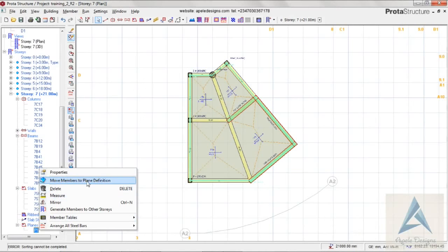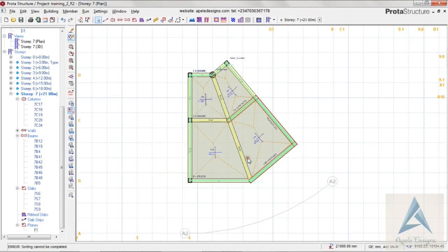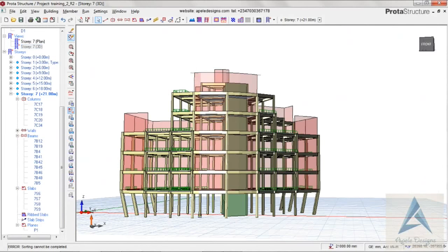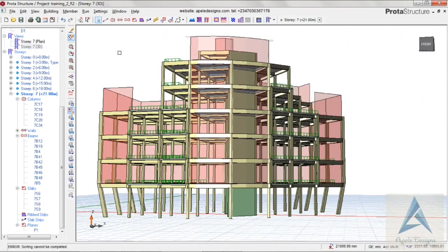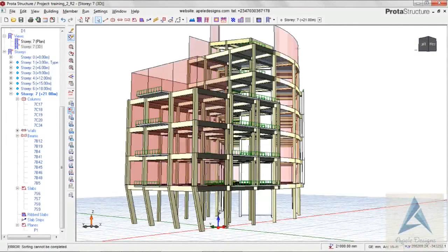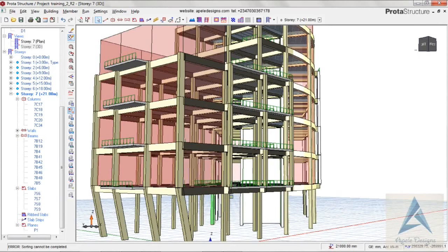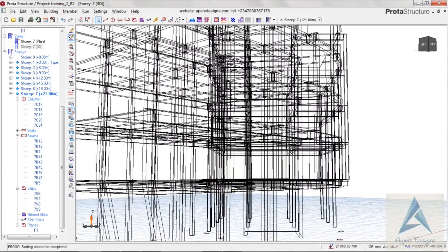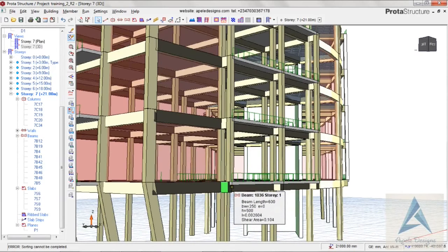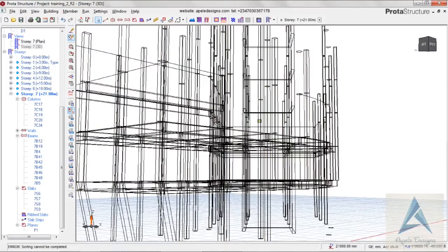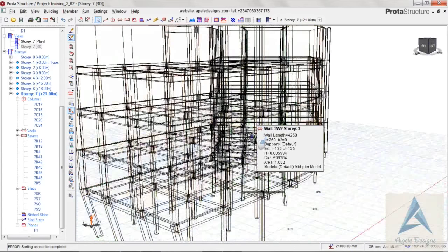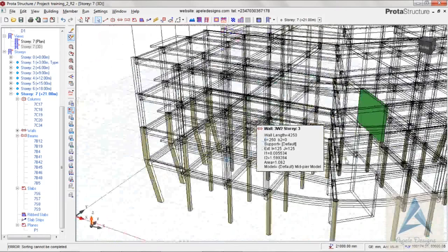Escape and escape. We'll do this again for the right hand side. Offset, give it a positive offset of 1000. Hit F2, 1000. Enter, escape and escape. And we'll repeat the same process for the ones in front. We'll click, right click, offset, take it downwards, F2 minus 600, escape and escape.